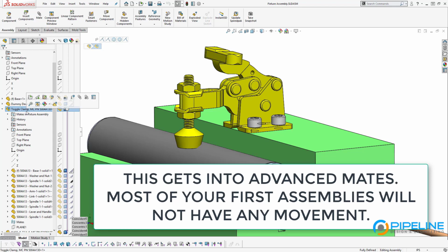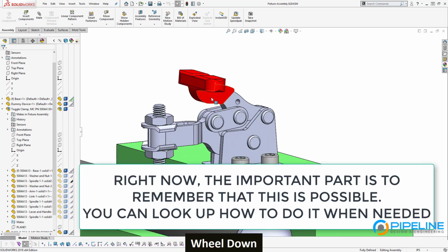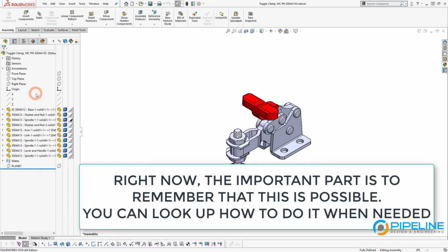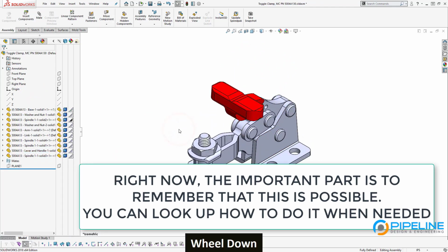We call it a sub-assembly because it is an assembly, but it's not the assembly we're working on right now, right? This sub-assembly is included in the entire assembly that we're using here. So by default, SolidWorks won't let you move parts around that are inside of that sub-assembly. If I opened this and grab the handle, it still works.